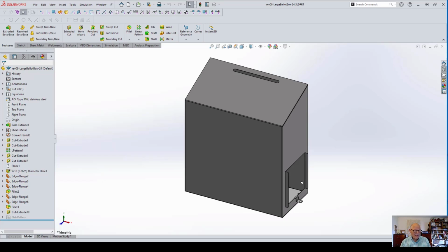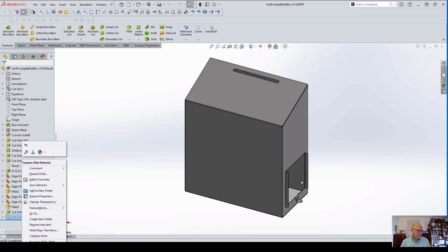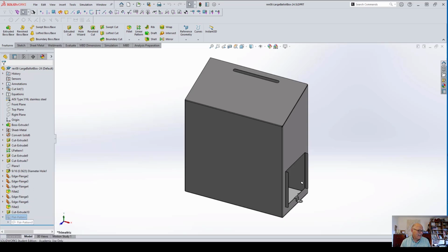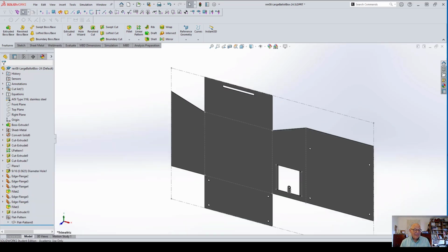But I was always amazed that my uncle could figure out the flat pattern for something based on how it was supposed to look, because he couldn't start with this shape. Instead, and I'll show you what I mean here, that's the flat pattern. So what he would have to do is make a pattern, mark it up. My job, and the other people in the shop as well, would be either to cut or to fold at these fold lines, and when it was all done, fold it up. Then we'd have to go back in and weld it up.